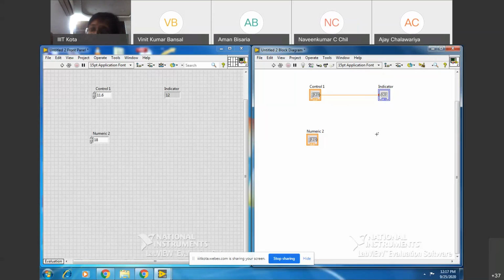But LabVIEW allows some mismatching, as it allows the compatibility. So what it is doing, it is converting the floating point number to the integer, and that is the result. But it says there is a mismatch in the data. So it is inherently giving a warning to you, right? So this is one way of looking at that. Okay. So I think this is one.